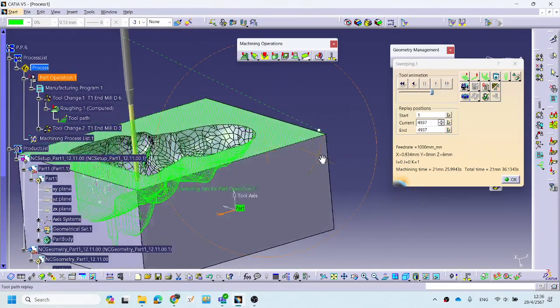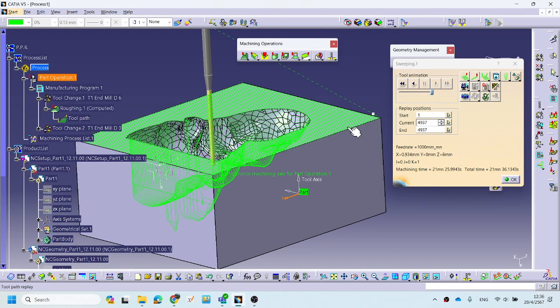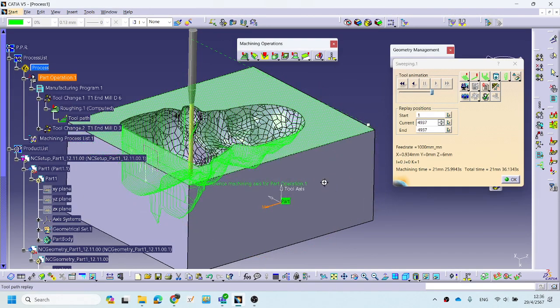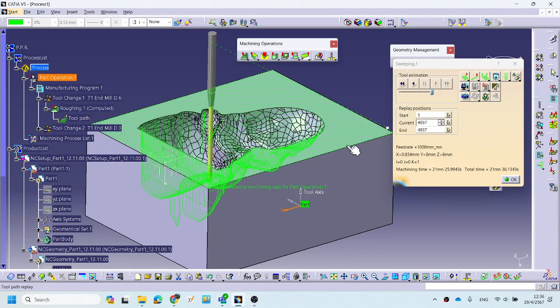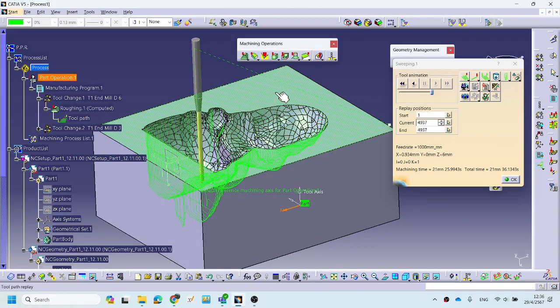These two cut on the top surface of the workpiece. If you need to avoid this surface being cut by the tools, because you need to keep it transparent, because maybe the material used is acrylic. This is acrylic. Okay, if the top surface is being cut by the tool, the transparent surface is gone, right?